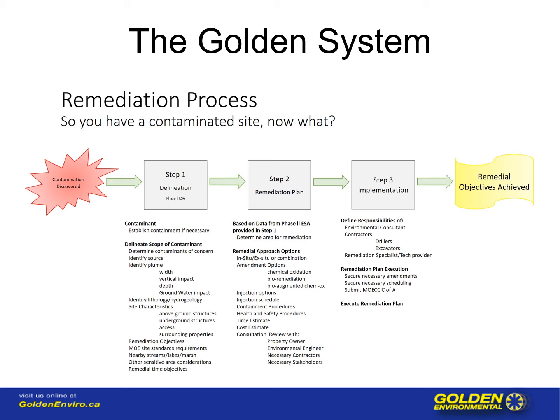Then we have to look at the lithology to understand what soil oxidant demand will take up energy from our amendment. This needs to be combined with our chemical oxidant demand. This is a very important step, and we must identify what type of soil we are dealing with in order to inject the proper amount, enough chemical oxidant.